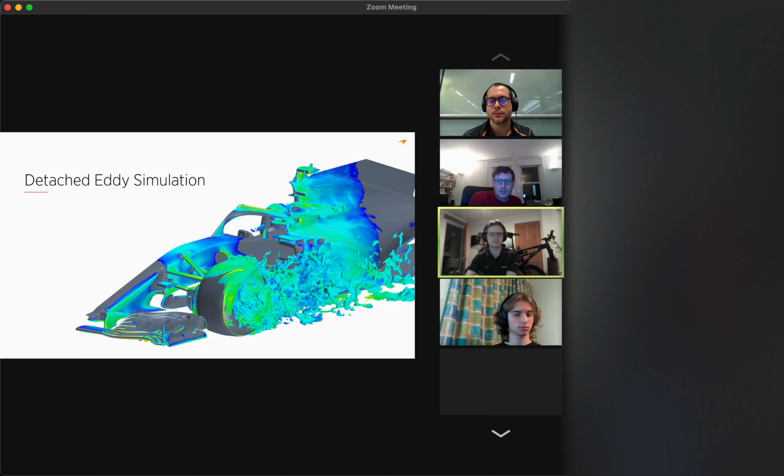But there's a compromise, and this is called detached eddy simulation. The most expensive bit of a large eddy simulation is where lots of interesting things are happening, which is next to a wall, like on the surface of a car. So what you could do is run LES away from the wall, say in the wheel wake, where we want to know what's happening with all these complicated structures, but near the wall we'll use RANS because it's cheaper.